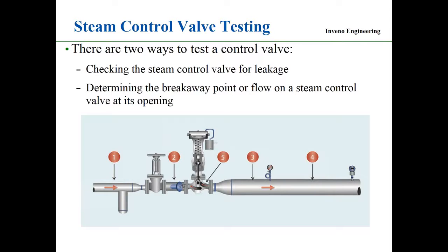So this control valve can accept a 4 to 20 milliamp signal into the positioner, or 3 to 15 psi in the positioner, or if it doesn't have a positioner from the I to P, 3 to 15 psi. As I start to apply the control signal into this valve, at what point does the valve start to pass steam? So if it's 4.0 milliamps, I go 4.4 milliamps, is it passing steam yet? Or does it start to pass steam at 5 and 5.5?